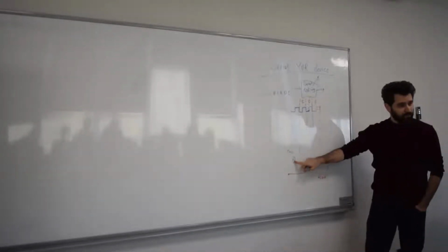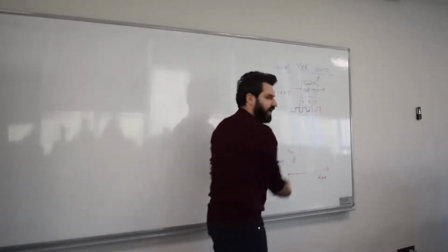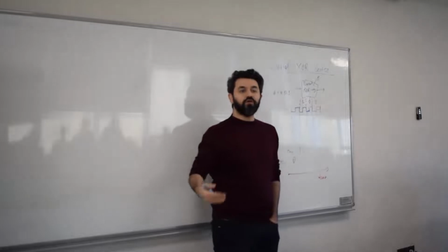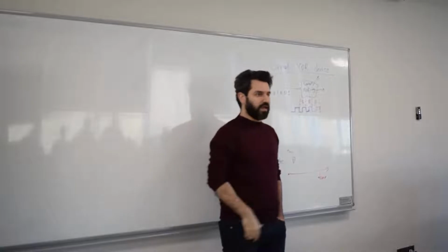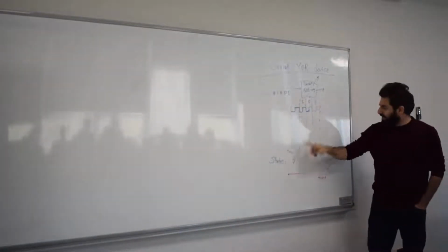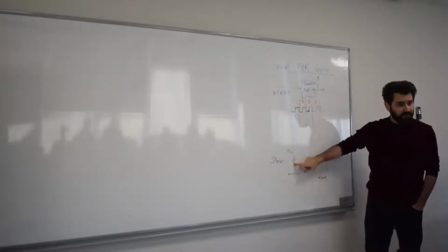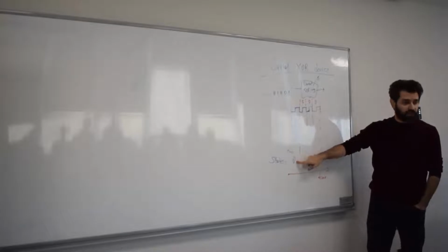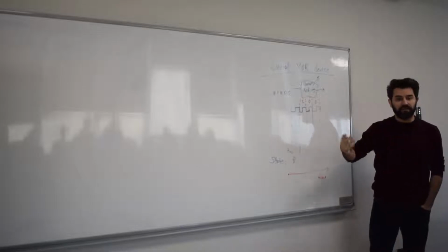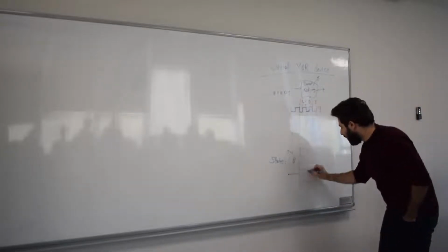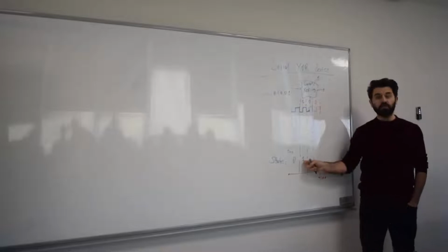So what is this circuit supposed to do? It's going to take the 0, this is the state. State meaning the flip-flop state. That's what the flip-flop stores. A flip-flop is capable of storing only 1 bit, remember? So it holds that 0, and then at the particular period, the input is 1. What this device is doing is it gets that 1 and that 0, and then these two get XORed together. So you get a 1, right? That is your output, but it is also your new state. So your new state now becomes 1.